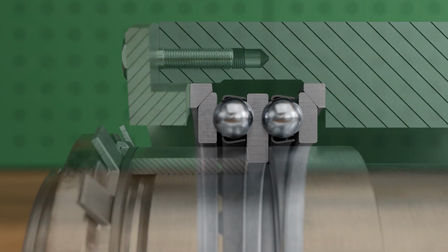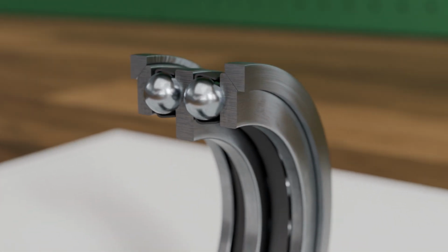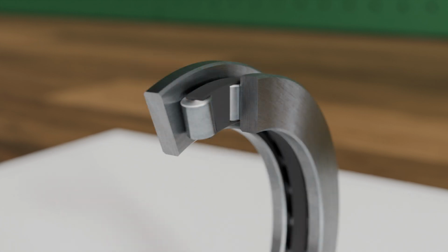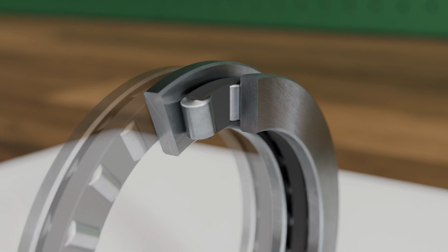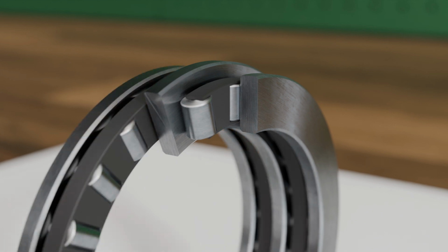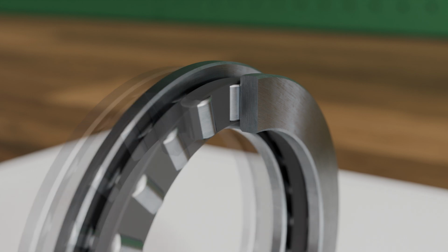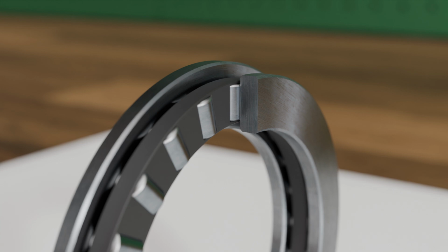The axial load capacity of ball bearings is limited due to the point contact between the spherical rolling elements and the raceways, which leads to high surface pressures. For heavily loaded applications, cylindrical rollers are therefore used as rolling elements, guided between two washers. Cylindrical roller bearings are available not only as single-direction bearings but also as double-direction bearings, which can absorb axial forces in both directions accordingly. Thrust cylindrical roller bearings can carry significantly higher axial loads than thrust ball bearings, but they are more sensitive to misalignment and generally achieve lower speeds compared to thrust ball bearings.